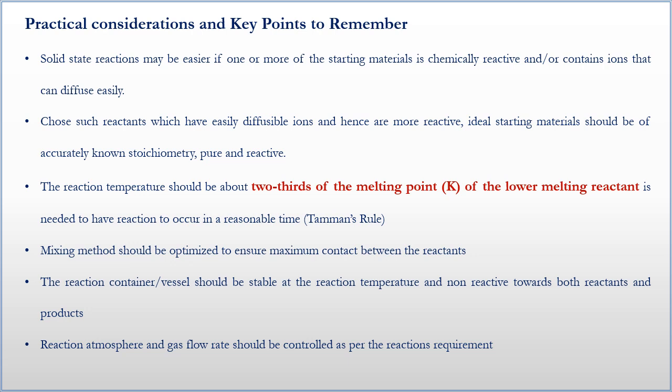The reaction container and the vessel which you are choosing should be stable at that reaction temperature. It should be non-reactive toward both reactant and product, and that also includes byproducts. The reaction atmosphere and gas flow rate should be controlled as per the reaction's requirement.